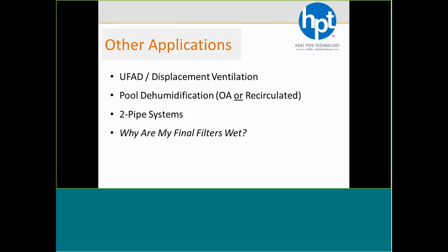Another call that we commonly get is when final filters are wet. And you've probably heard this before, some of you have, I'm sure. Why are our final filters all soaked? Well, typically it's because it's a blow-through fan configuration, meaning that the fan is not downstream of the cooling coil, it's upstream and blowing air through it and then through the final filters.